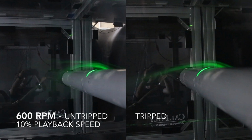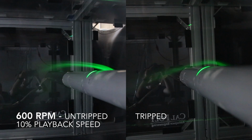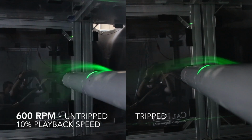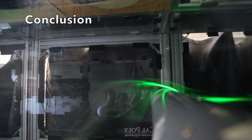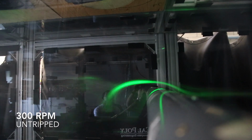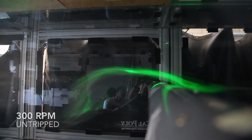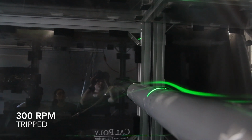Although the Strouhal numbers calculated for the flow around the cylinder at 5 meters per second were not accurate, it can be seen that the frequency at which the vortices were shed from the cylinder was reduced when the boundary layer was tripped by the sandpaper strips. From the flow visualization in the two tests, tripped and untripped, it is clear that adding roughness to the surface of the cylinder tripped the boundary layer and allowed the flow to stay attached to the surface of the cylinder longer. This is because adding roughness increases the energy of the boundary layer.